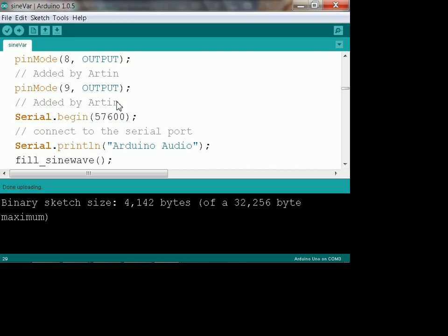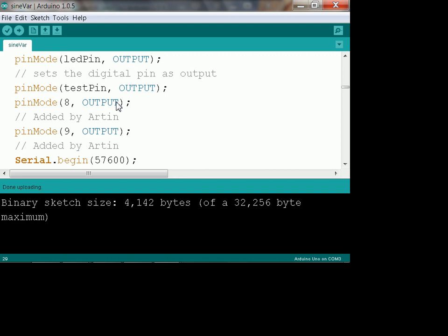Okay. So then when you look at pin modes output, that's just what it says. You look at some of these pins here and you can kind of see them. If you stare down at your audio shield, from the top, you'll see there is a pin 9, and if you look real carefully at pin 9, you'll see there's a trace that goes right over to one of the resistors, and I believe it says R5.